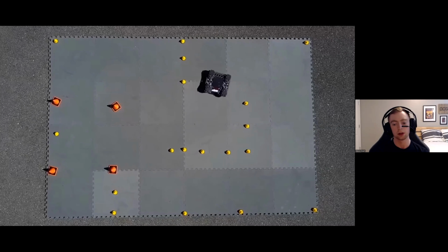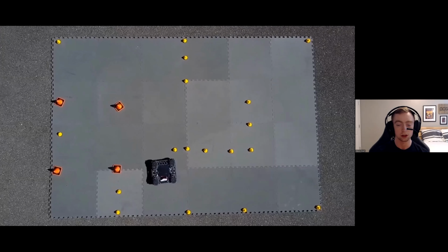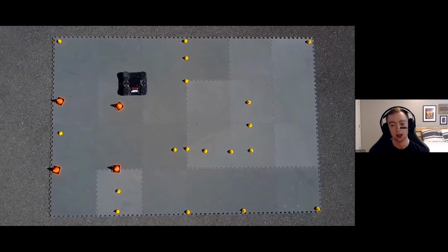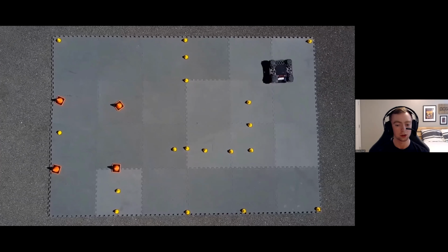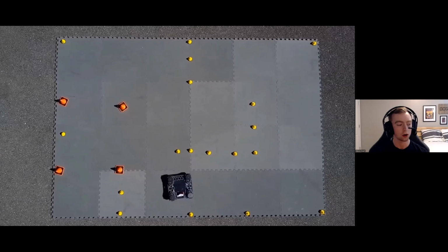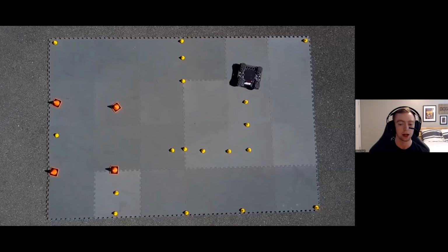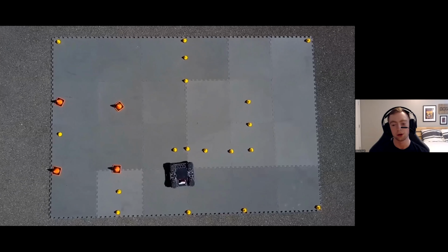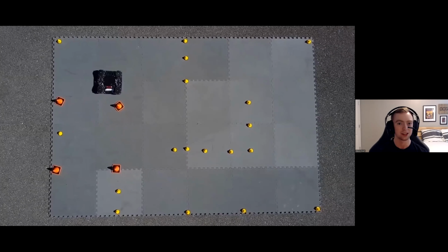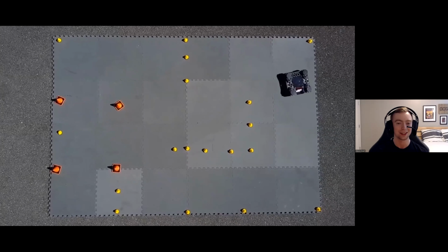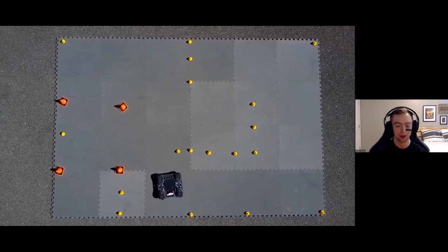And then here's a video of what the very first version of the Swerve looked like when driving. This is the summer version. This was the dual goBILDA Super Speed version, and as you can see, there are a lot of small issues with it, such as heading instability, random jittering, and more. This was largely in part due to the mass testing that this first design underwent, as well as static issues when originally filming this video.